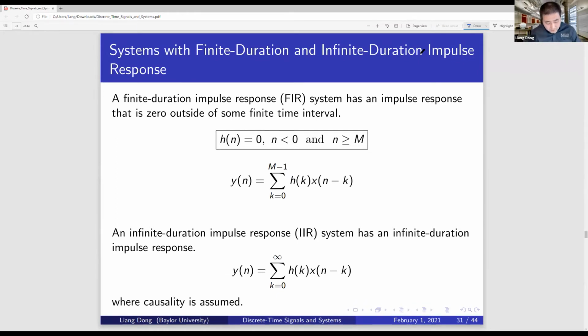We mentioned last time that an impulse function, if you look into the frequency domain, is just constant across the whole frequency range, across all the spectrum. So it gives me all the testing frequencies you excite the system with, and then you check the output. Of course, you know everything about the system. So once I get the response to an impulse, I know the system in its entirety. I can use that h[n] and work on any arbitrary input x[n] and get the actual output, y[n].